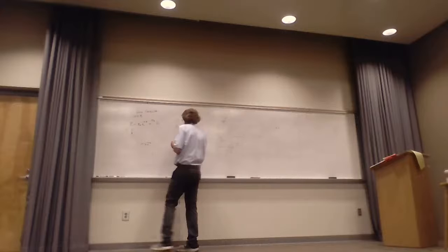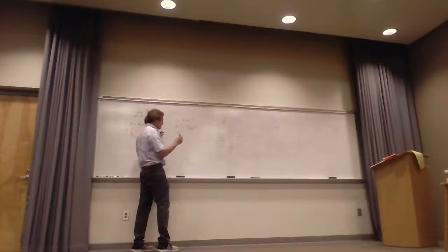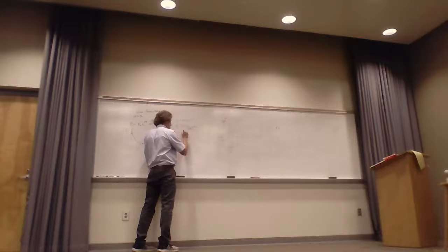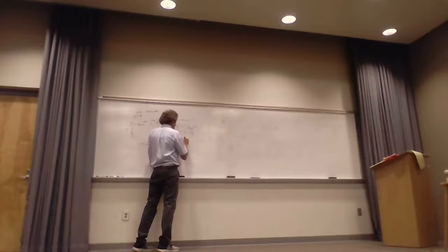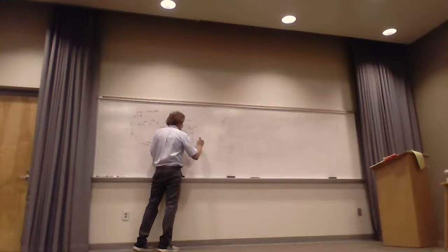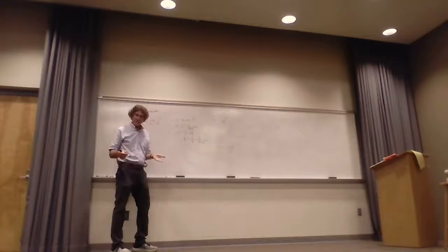And then the third thing you did in EMAG 1 back in the day, you found the E field because you know that J was equal to sigma E. This is low frequency or DC. And therefore, the E field itself was equal to J over sigma, or it's I over pi a squared sigma a_z. Y'all remember doing this stuff?